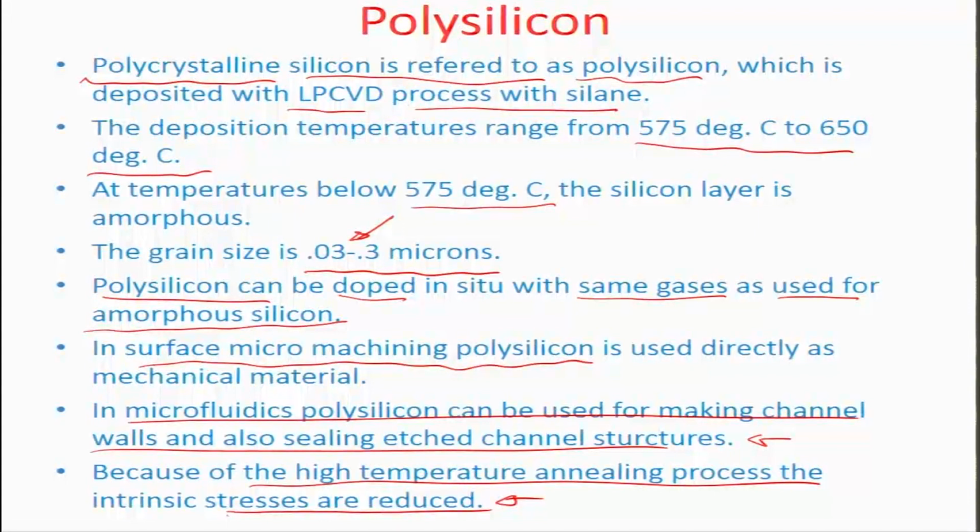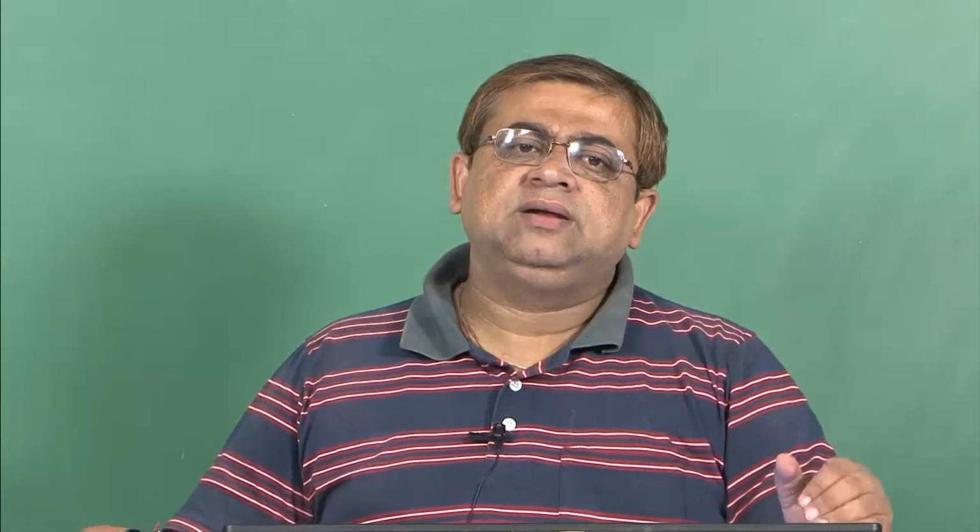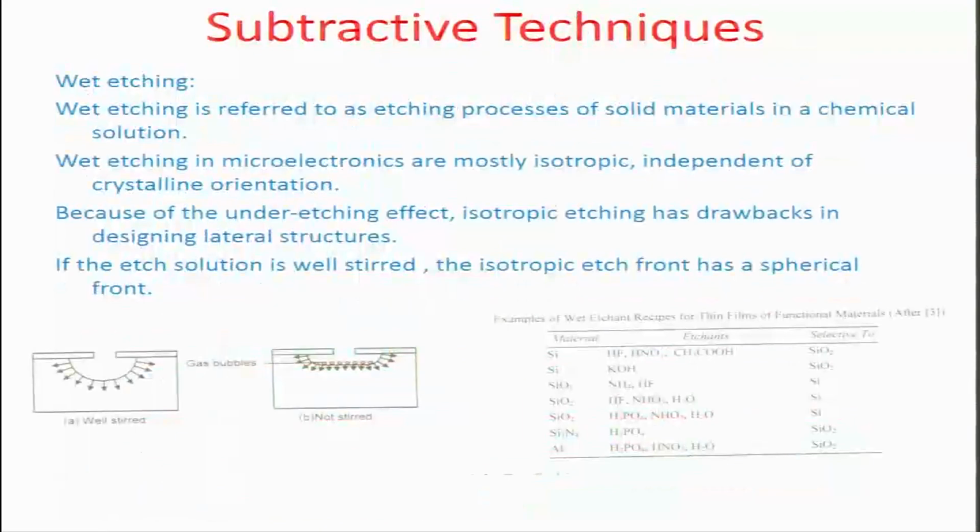So, silicon now can be obtained in single crystalline form directly from the growth process, or it can be grown using epitaxial methods, where you have deposition of silicon atom by atom, layer by layer, and then you have the third form, polysilicon, which is polycrystalline growth in multiple nucleating centers with grain boundaries, which is mechanically the most robust system of crystalline silicon that can exist. So, that is how silicon can coexist in its different forms.